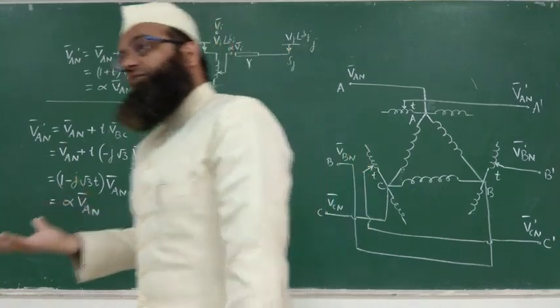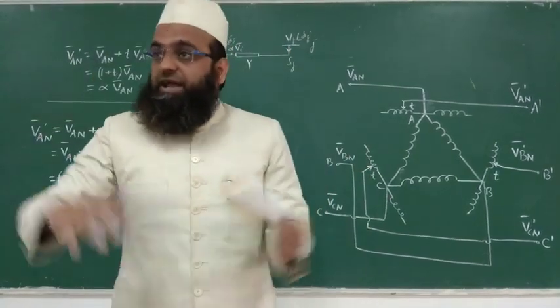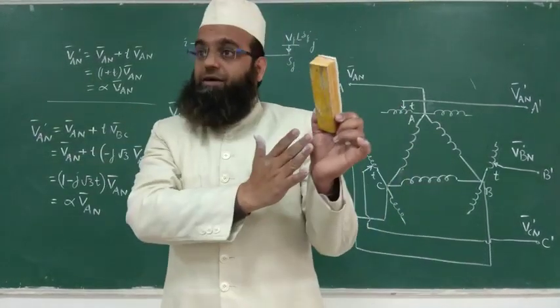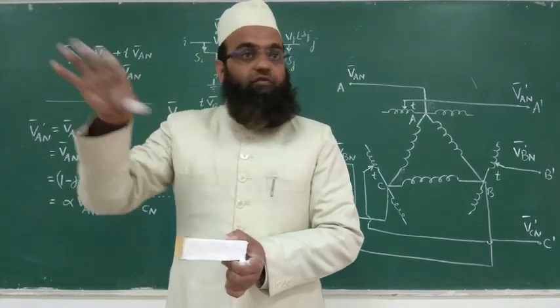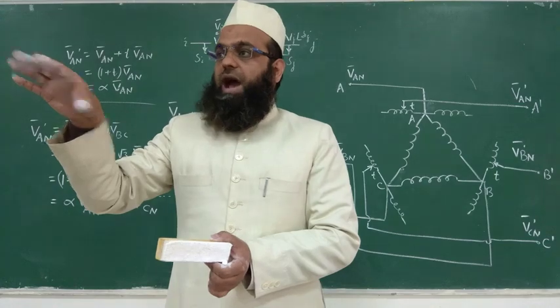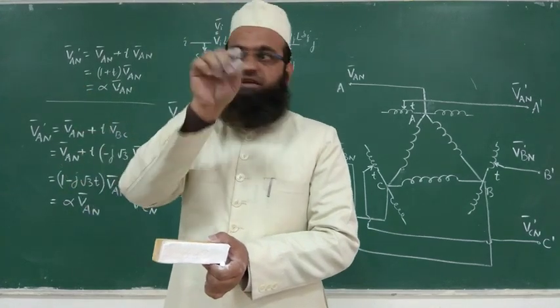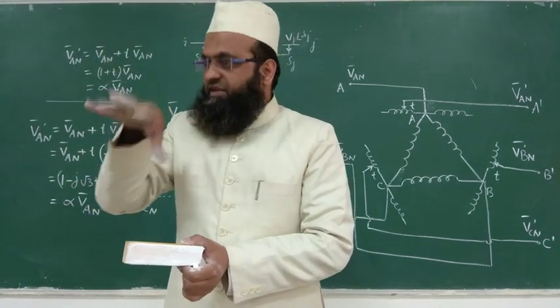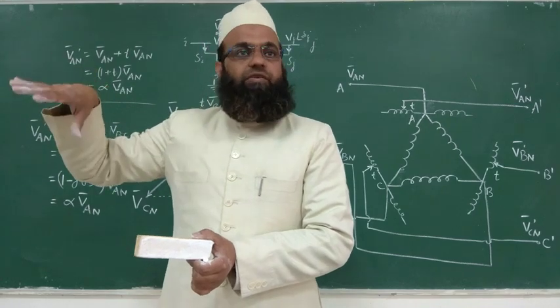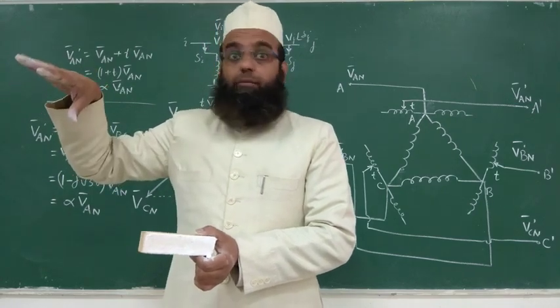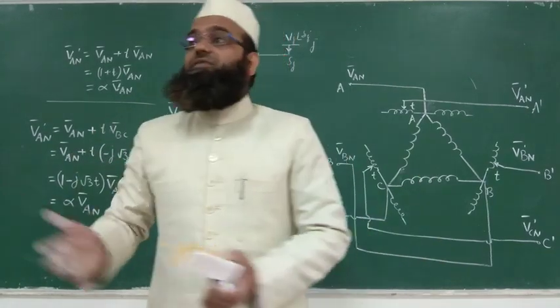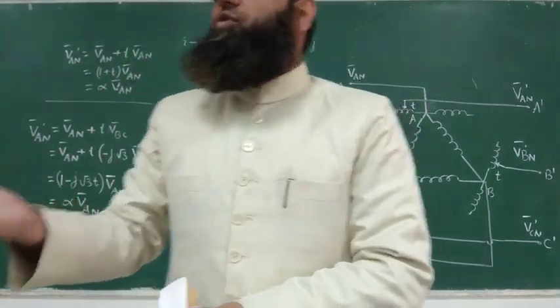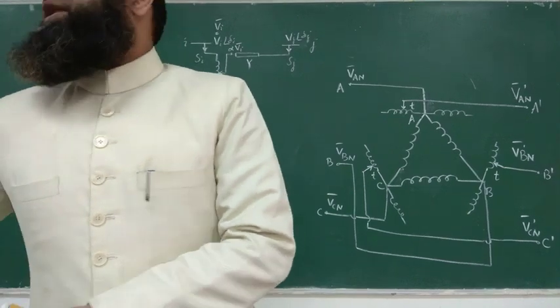So for Y bus formation, you have applied KCL corresponding to I phasor, Y phasor and V phasor. Is it not? I phasor is nothing but the bus admittance matrix times which phasor vector? Voltage. But now that voltage phasor has been modified. It depends on which bus you are going to use a regulating transformer or any other means.